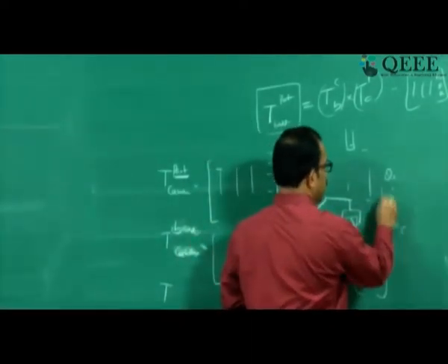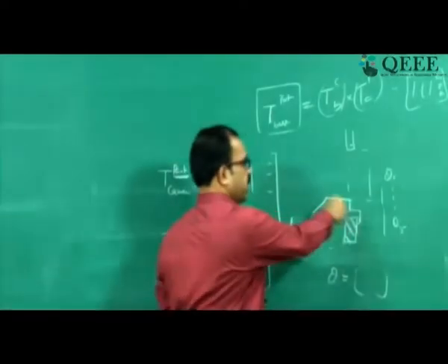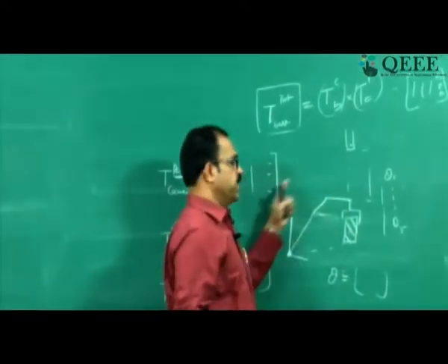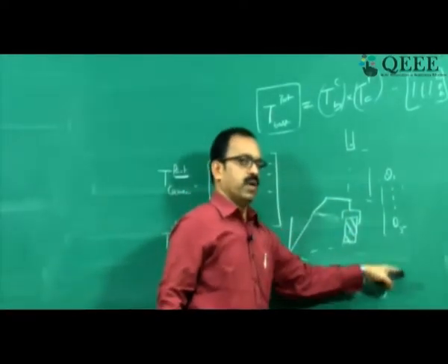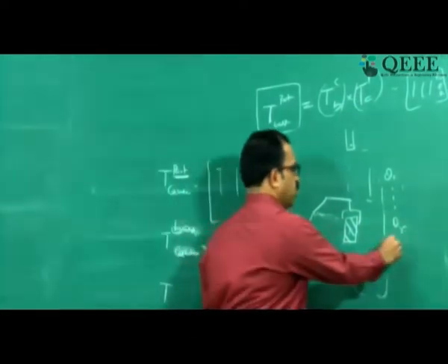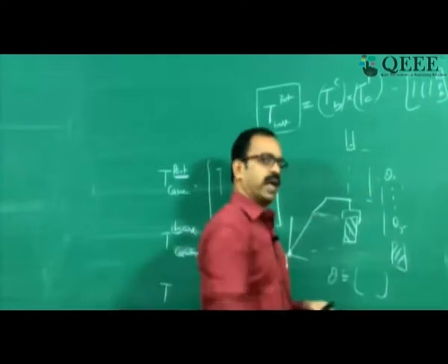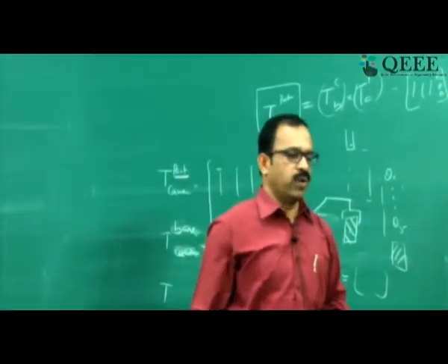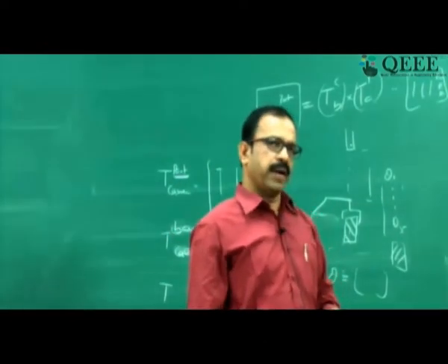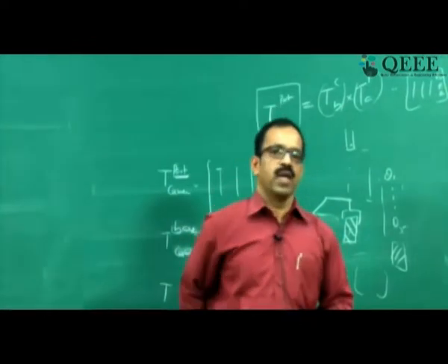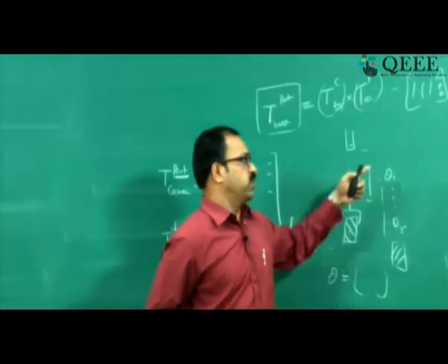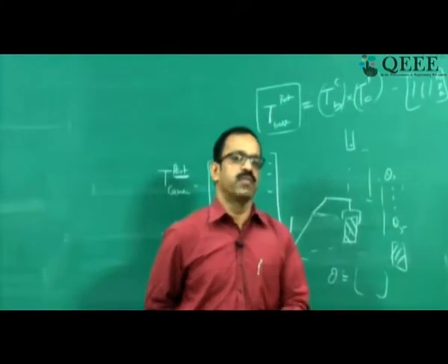You will be getting theta 1, theta 2, etc. So theta 1 to theta 5 can be solved, and the robot can be actually moved to grab the object. And again it will do an inverse kinematics to see where to go to the bin, accept bin or reject bin, which will also be carried out. So that is the way a real robot works using inverse kinematics.